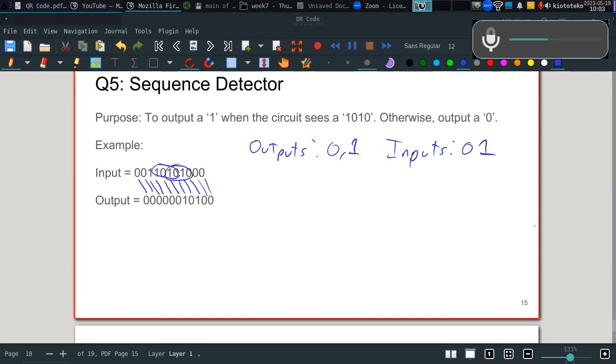With which finite state machine? Would it be a Moore machine because it's all offset by one? It would be with a Mealy. With a Moore, I think 5, but with a Mealy you would get 4. But yeah, with a Moore you may get 5. I haven't done it with a Moore, but I know with a Mealy it's 4 states. So let's just start this time with a Mealy machine.